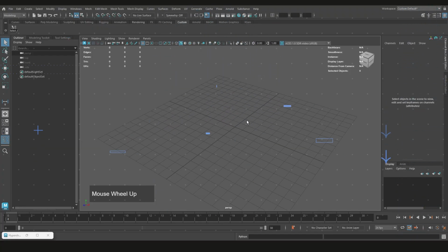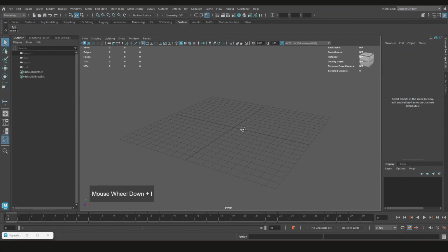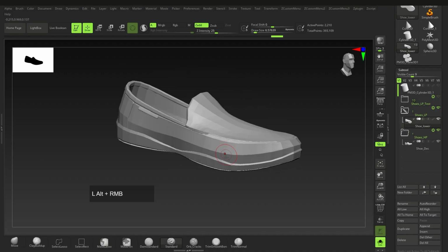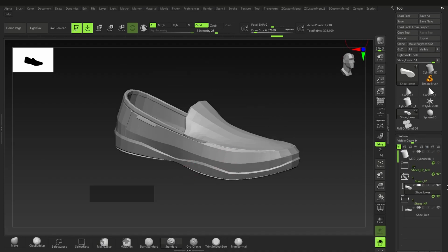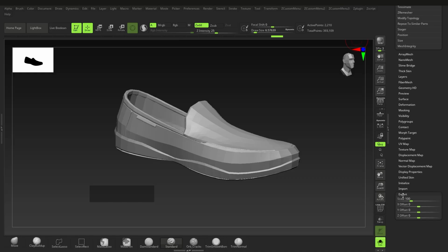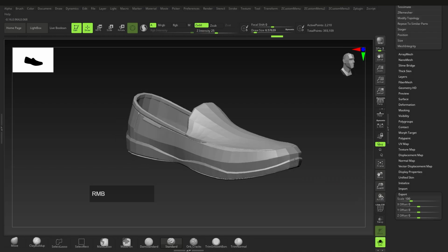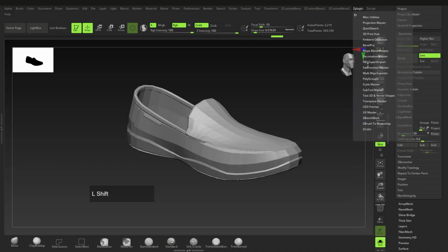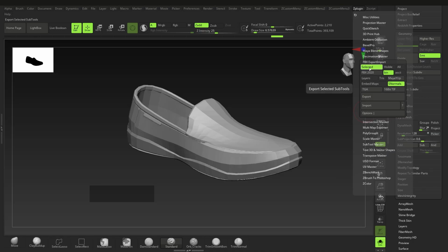So now that we actually have everything set up, our scaling, saving, etc., let's actually export the ZBrush stuff. Okay, we can export this. We'll do FBX. And oh yeah, we don't know our scaling here. Here the scale is at 100, so for the export settings, make sure this is all on 0, and this as well. I have it at 100, but we'll see what it does. So ZPlugin, FBX Export Import, which is here. The selected mesh, yes. All of this should be fine. Smooth normals, sure. We'll go to export.